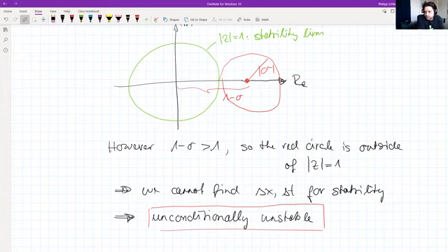Again, that's because of the superposition principle. But once this is fulfilled, or can be made to be fulfilled by a suitable linearization, then the von Neumann analysis is a very helpful tool in order to determine stability. And most of our simulation codes, they use von Neumann analysis somewhere inside. Okay. Do you have any questions regarding stability?